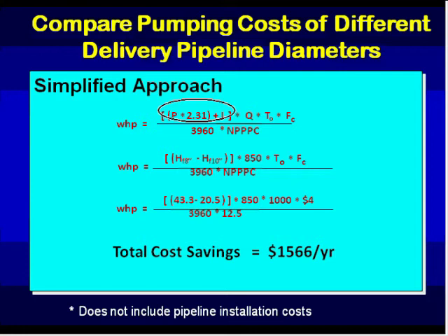We're going to multiply by the flow rate here, the time of operation, and our fuel cost that we have here. And then we're going to divide by 3960, which is the coefficient to convert all these numbers to the right units. And we're going to multiply and also divide by the Nebraska Pumping Plant Performance Criteria for diesel fuel. So if we put the numbers in our equation, we're going to have 43.3 was our original one.